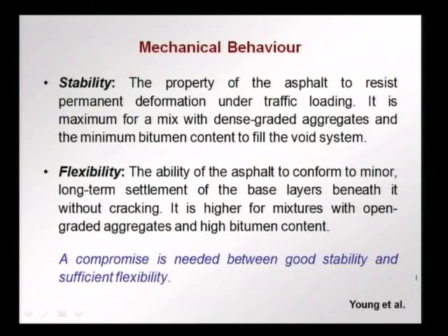We also have to look at the concept of flexibility. Flexibility is the ability of the asphalt concrete to conform, to follow, to adapt to minor long term settlement of the base layers beneath the asphalt concrete without cracking. Suppose there is the subsidence of the subgrade, subbase or base layer a little bit.